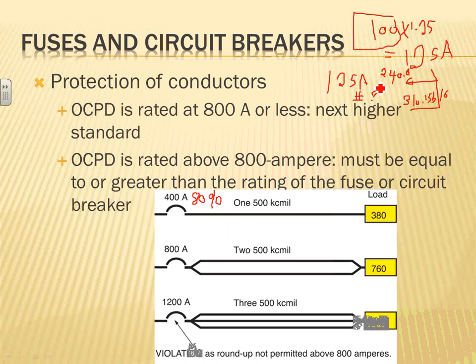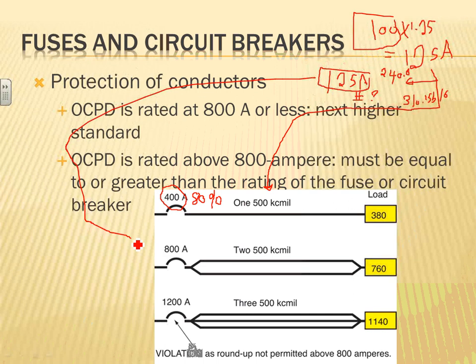And then when you put your conductor right here, you size your conductor. You came up with 500 kcmil. Your overcurrent protection device can be slightly higher than what the conductor is rated for. Now, if this process landed you in the 1200 amp, then I start using the 1200 amp, not the actual load, to size my conductor.